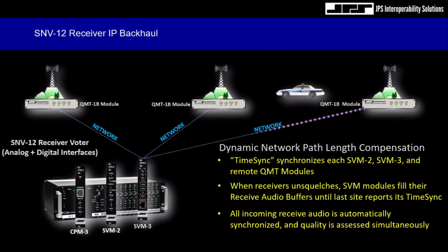The amount of audio to be buffered is based upon the instantaneous timestamp at the moment the site transitioned into an unsquelched state. So we're forcing early arriving receive audio to be stored in the internal digital signal processors, which are the buffers, to wait for the late arriving receive audio. The audio buffers will then breathe as the network latency changes throughout the day.